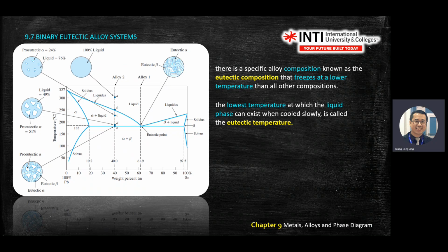You see where the lowest point of the liquid phase is, because all these are solid already. So you drop until you see the lowest point. You see one lowest point. That is called eutectic. You draw a straight line to the left and then write that one as eutectic. Then you write in your answer, eutectic temperature equals what?